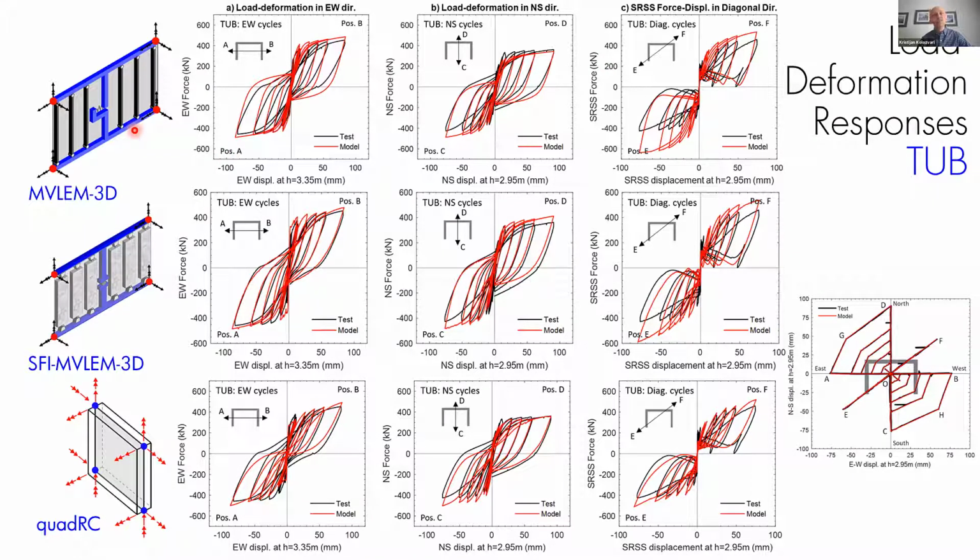So it's kind of like a beam formulation, Bernoulli-Euler assumption. And because of that assumption, you simply cannot predict the nonlinear distribution of strains along the cross section of the wall. We will actually look at those results in a second, and you will see exactly what causes this.